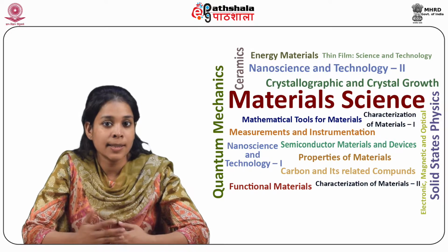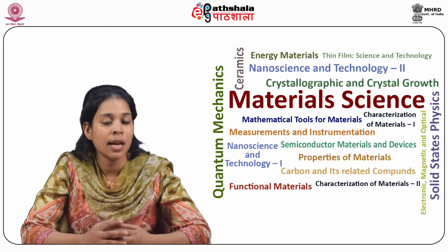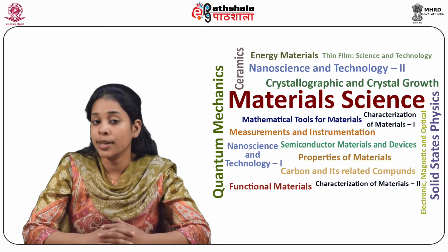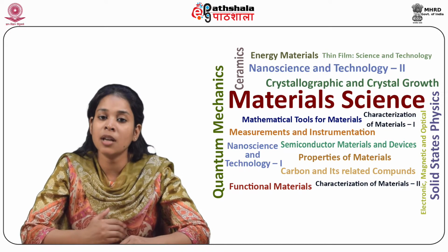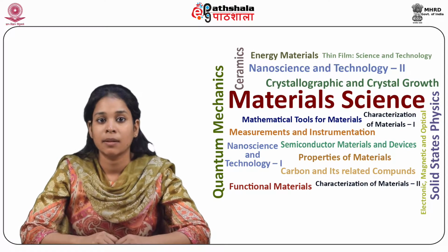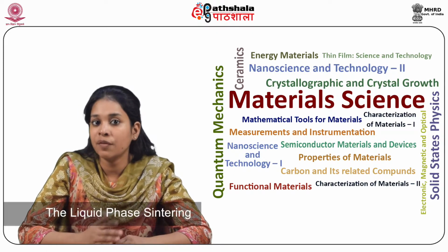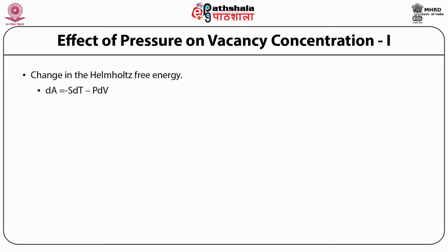During solid state sintering, no significant amount of any liquid phase is present. However, in many cases, a liquid phase is present during sintering. The presence of liquid phase in these cases gives a high sintered density at very low temperatures. In this module, pressure assisted sintering and liquid phase sintering will be focused and discussed. Now first we are discussing the effect of pressure on driving force and vacancy gradients.